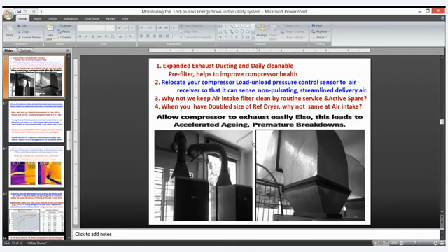Again, the end-to-end energy monitoring comes. For the boiler, we monitor the flue gas and try to arrive at the indirect efficiency of the boiler. Similarly, let us look into the indirect efficiency for the compressor also. We are not trying to calculate the efficiency of the compressor, but what is all wasted. The heat of compression for a given compressor is almost 60 to 70% that is going out as exhaust at the exhaust hood of the compressor.